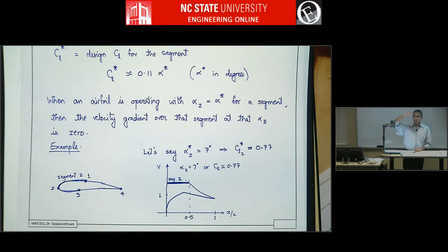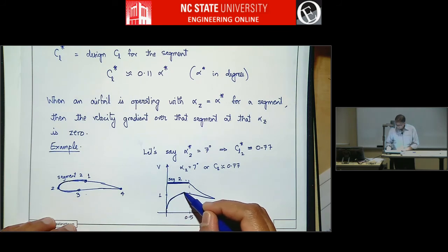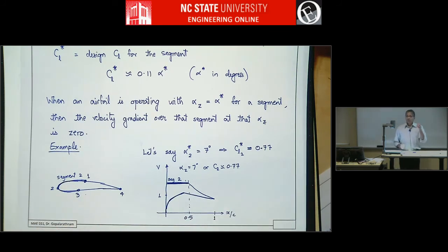The CL for the upper corner of the drag polar. Like that, if this segment's alpha star is 2, the lower corner of the drag polar will be close to 0.2, 0.22, something like that, 0.25. And the details will depend on the Reynolds number, so you always need something like Xfoil. If you run it, then you'll get a polar, and then you can start moving it around by changing these numbers.